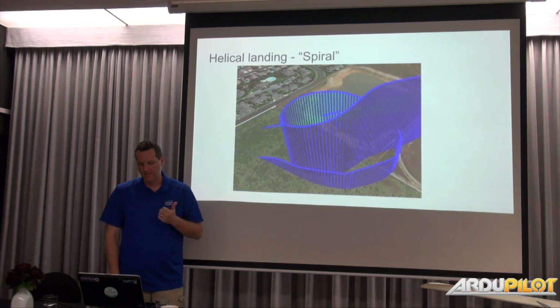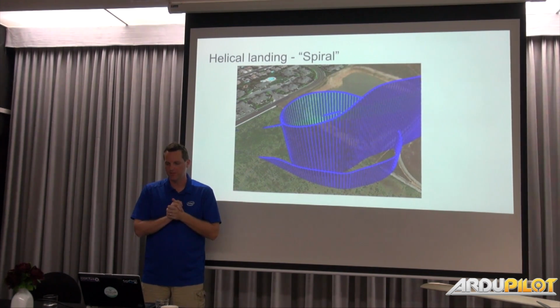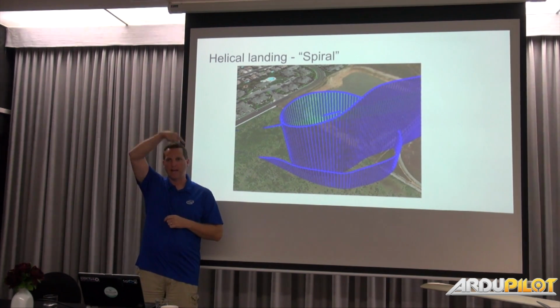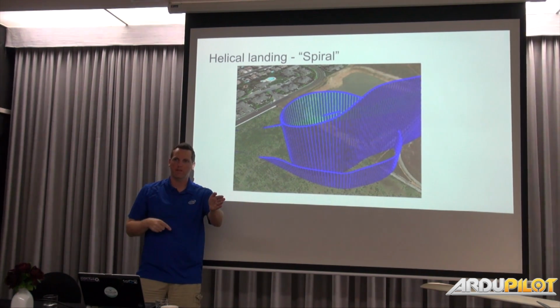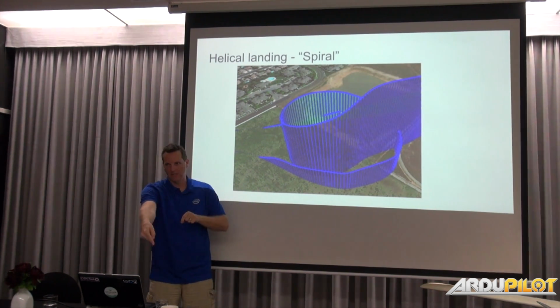Helical landing. So I did some testing with this. I don't know if anyone's actually doing this, but I wanted to show how I've done it. These were done with Skywalker X8s. So that is coming back, you just loiter down, and then when you come out of the turn, you want to be lined up with the runway. If you line up the points in the middle, then you're going to be doing this weird turn thing as you're landing. So you don't want to do that.